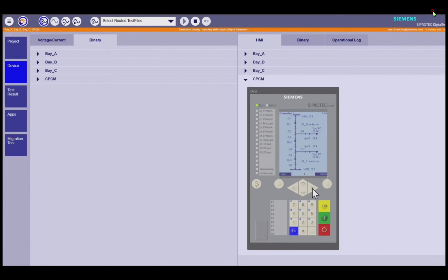In the next page, we have the values for the synchro check function, which voltage is selected for this application for each circuit breaker 1, circuit breaker 2, and circuit breaker 3. And then we have the operational values for line 1 with the active power, reactive power, and frequency, and also the operational values for line 2.